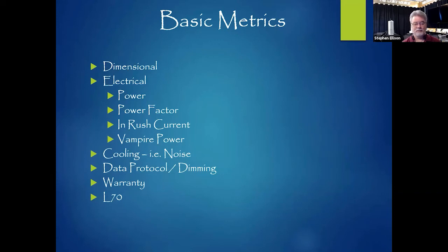Inrush current's major change is that the power supply can draw that much more power for that very short period of time. So that becomes an interesting thing to worry about. You might say, well, I don't have a problem. And the first time you throw that breaker, it pops immediately, and suddenly you don't have control, your lights just don't work.